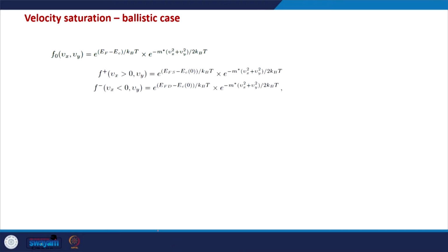So, now we can see how this saturation thing is coming into the picture in our case. In a MOSFET, if we just draw the barrier, this is how the barrier is without any VDS. This is the source side, this is the drain side, and this is how the barrier becomes when a drain voltage is applied in the system.